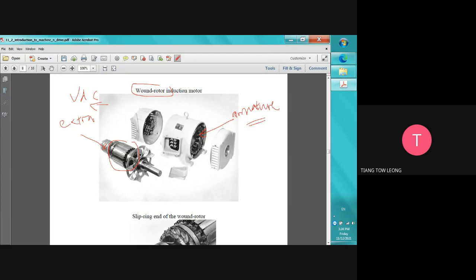The armature is the thing where, if we rotate the rotor, we collect the current or power. Or we inject the power or current, then this will rotate by controlling the field here. So this is the main one. For example, we connect 230 volt here. Is this winding? We call it the armature winding. We cannot connect 230 volt here.